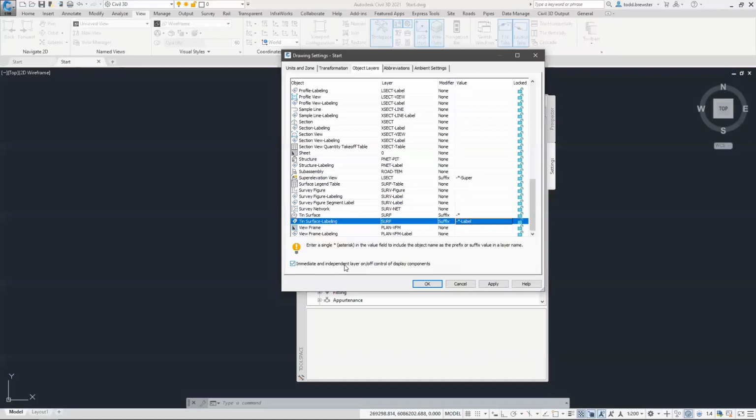So as I mentioned, all objects in the Civil 3D space can potentially have multiple components that make up the object. So alignments are typically made up of straights and curves, spirals, depending if you use them. You can actually specify unique layers for these in the styles when you create them. If this option is ticked on, then the visibility of all those subcomponents on different layers is not changed when the source layer is turned off.